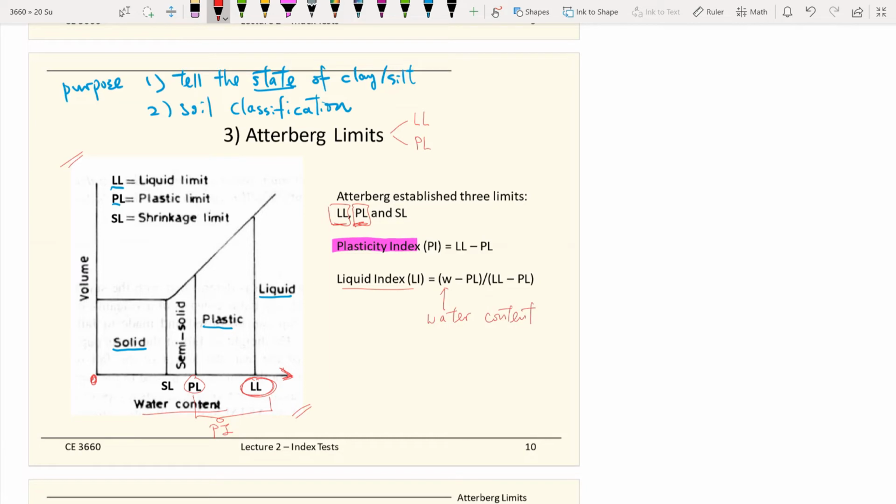So the plastic limit and liquid limit will highly depend on the soil type. Each different soil type, the soil in Los Angeles versus the soil in San Francisco, or the soil at your project site in East LA versus your project site at Long Beach. Every different site will have different soil, and you expect different liquid limit and plastic limit. So it's common practice that whenever you have a new project, you collect soil samples, ship them to the lab, and run the Atterberg limit tests to find the liquid limit and plastic limit for the soils you're working on at the site.